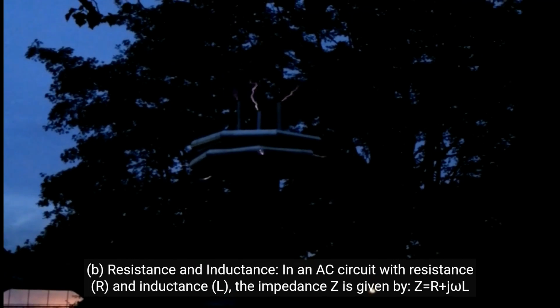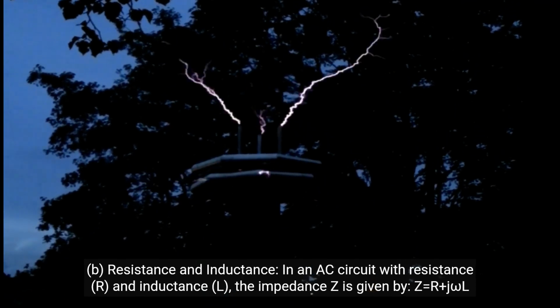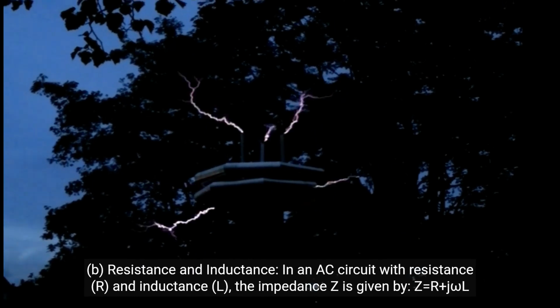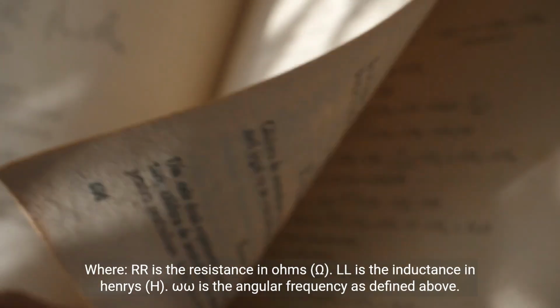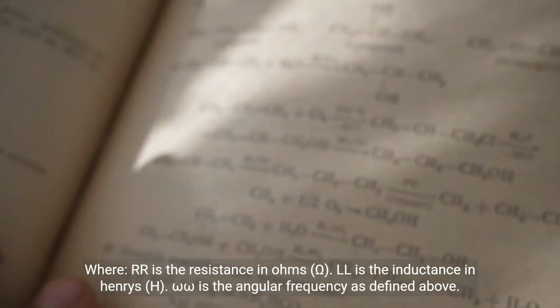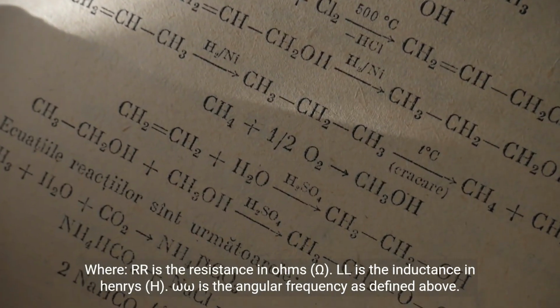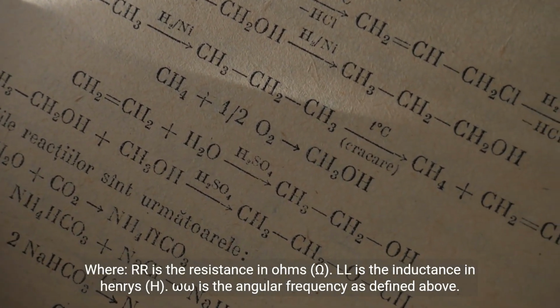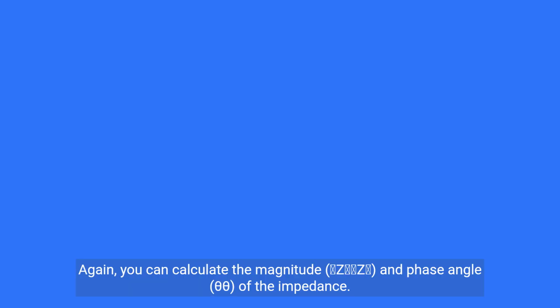B. Resistance and inductance. In an AC circuit with resistance, R, and inductance, L, the impedance Z is given by Z = R + jωL, where R is the resistance in ohms, Ω, L is the inductance in henries, H, and omega is the angular frequency as defined above. Again, you can calculate the magnitude, |Z|, and phase angle, θ, of the impedance.